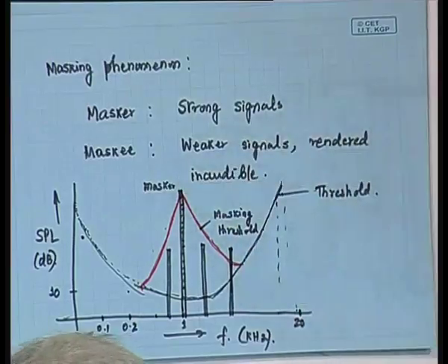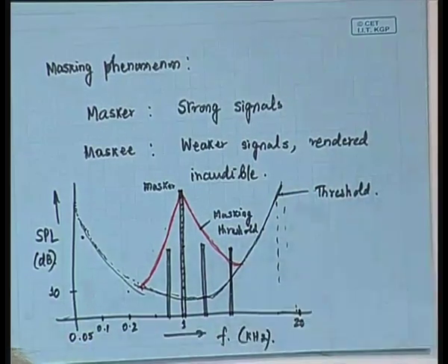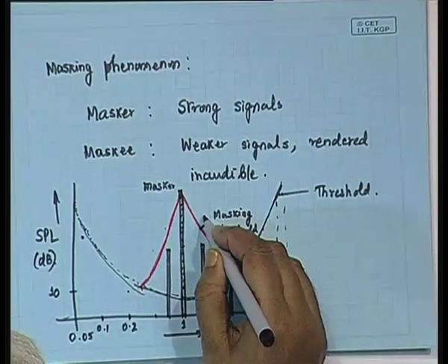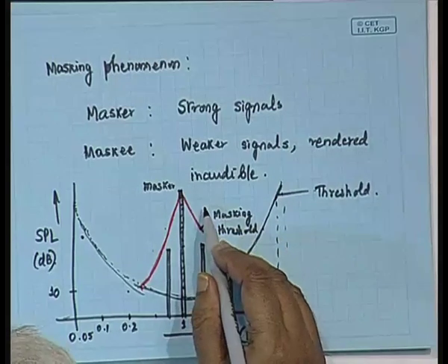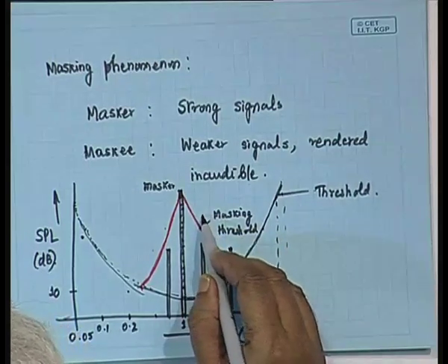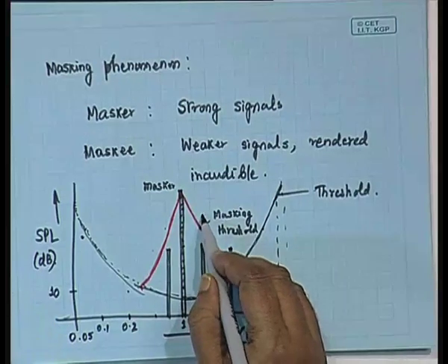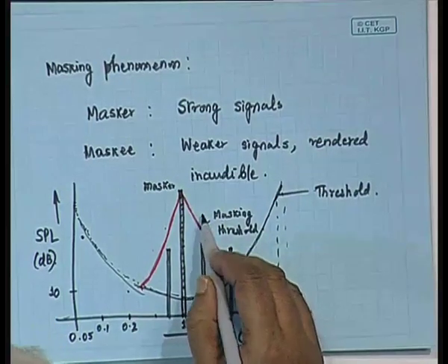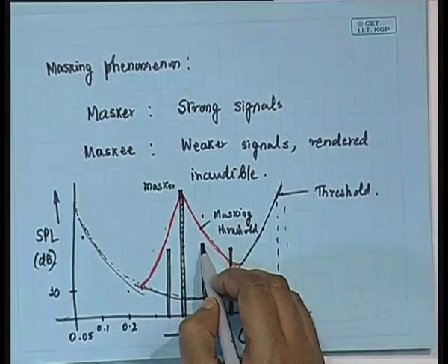If you have more bits, as you have seen, it improves the figure; the rough figure is 6 dB for every extra bit of allocation. So now the question is: if the masking threshold is this much, then by allocating one more bit, I am able to bring down the quantization noise from this one to this one by 6 dB, which is below the masking threshold.